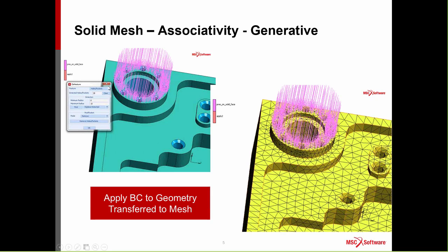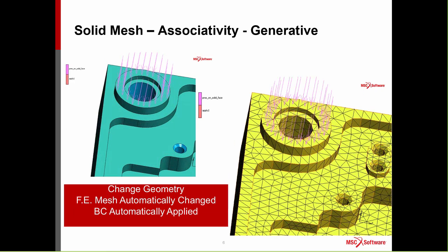But now if I say, let me remove the holes on this particular solid body, so I go into defeature and identify all the holes, and they show up in this lighter shade of blue, and then let's say I remove that group of holes, then effectively the holes are removed.